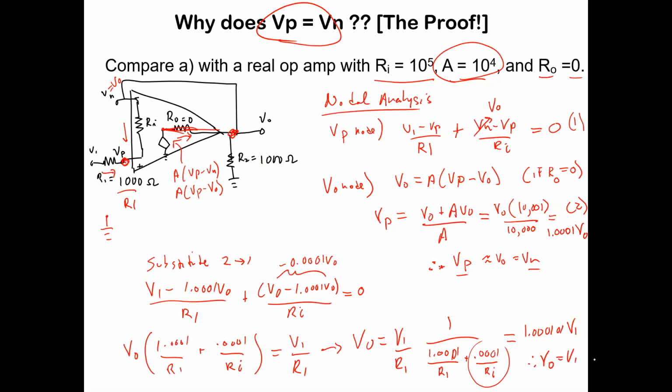That's like just saying that eventually your room temperature meets what your thermostat was set to. And you can now maybe get a sense of why it is helpful to have a really large A in an op-amp. It's like having a really big furnace in your house, right? If you want it to heat up really fast, having a big A could be helpful, and it scales the error by a huge amount, so it's extremely responsive.